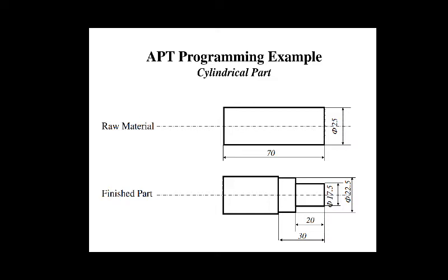We have seen the different G codes, G00, that is rapid traverse, G01, G02. So we have seen the various G codes, and we have seen the M codes, that is M00 program stop, M01, M02, M10, M11, M30. And after that we have seen the rules for programming. In that we have seen one block.